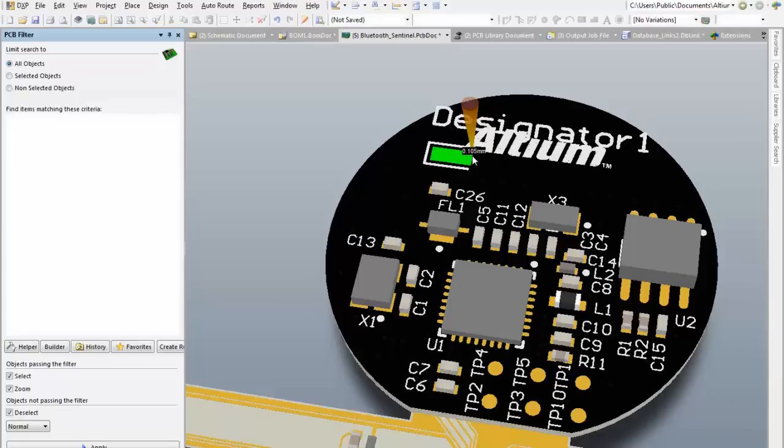And again, you can do that on your rigid board just as you would place any other components. The only key being, if you hit the tab properties, it will show that drop-down menu, and you can select the layer that you want to embed it to. So that is an example of how you would embed components within the Altium Designer platform.